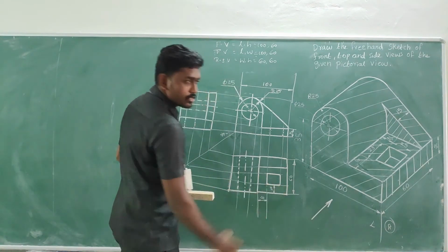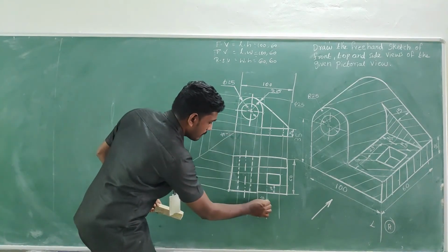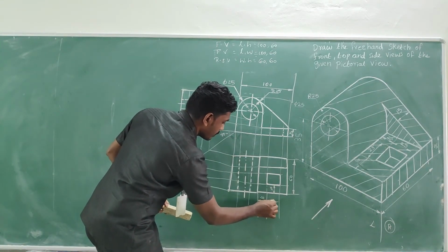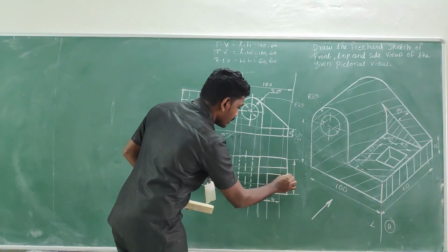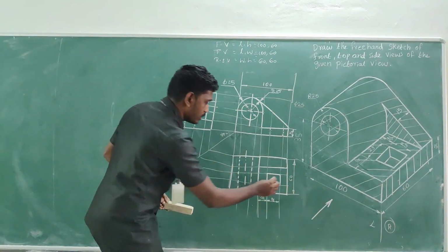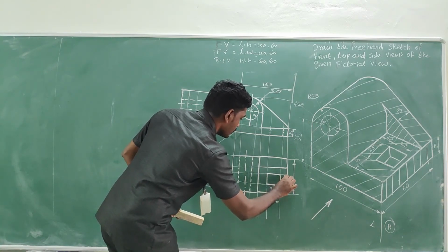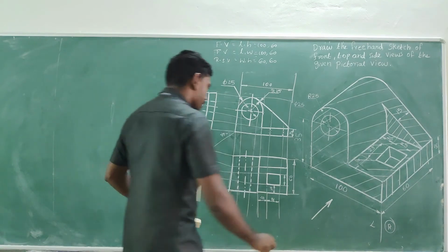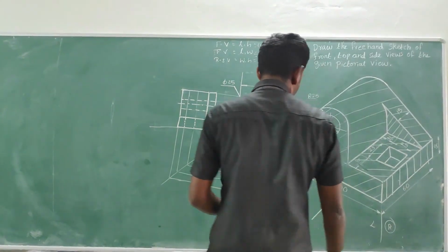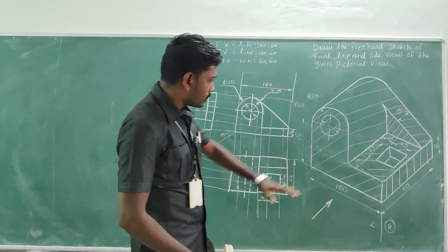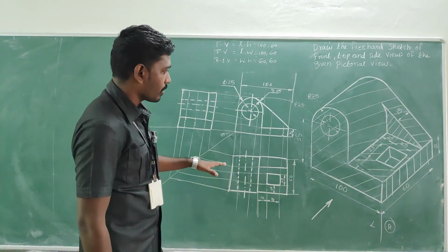And what about the side measurement? It is 25, right? So take the extension line and write as 25. And what about the width? That as well is 25, right? So inside it, without intersecting any of your visible edges, you can mark it right above it as 25. And then any other things regarding the top view? Any other measurement there? No, right? Almost everything we have completed.